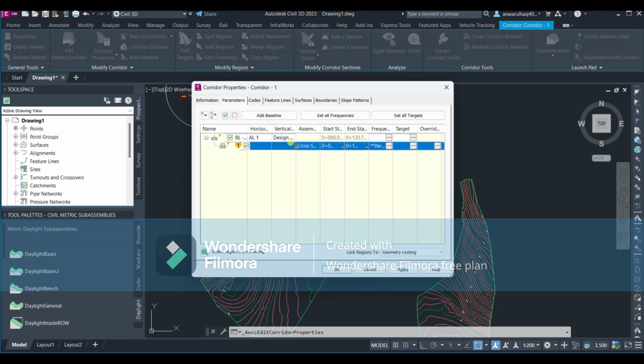Okay, so from here, start point, add one. Here you can right click and add region, insert region. As I already told you before, insert region is used to change the cross section. Because in this tutorial we have only one cross section, I will not make that change.